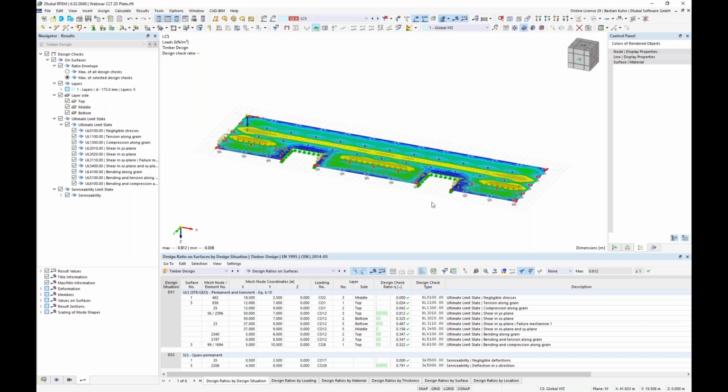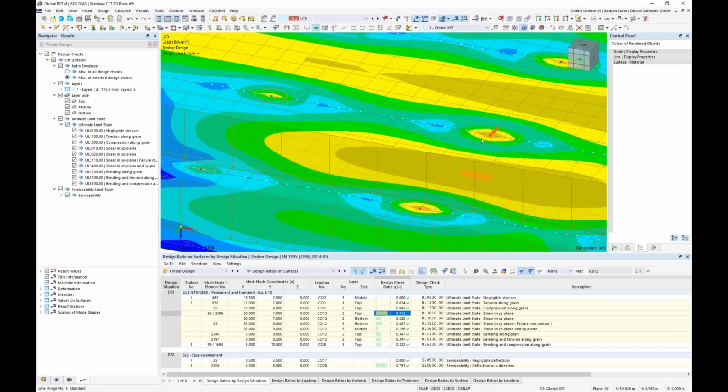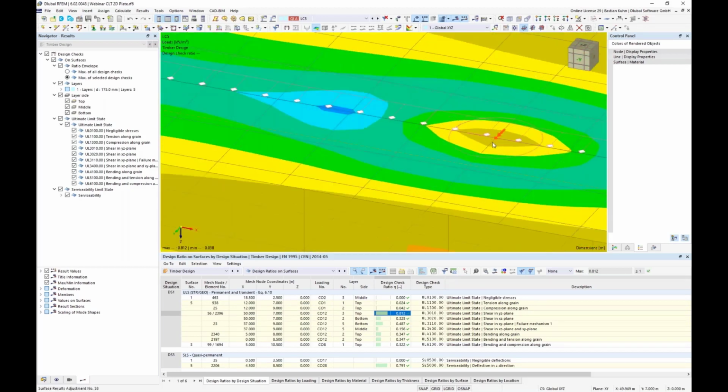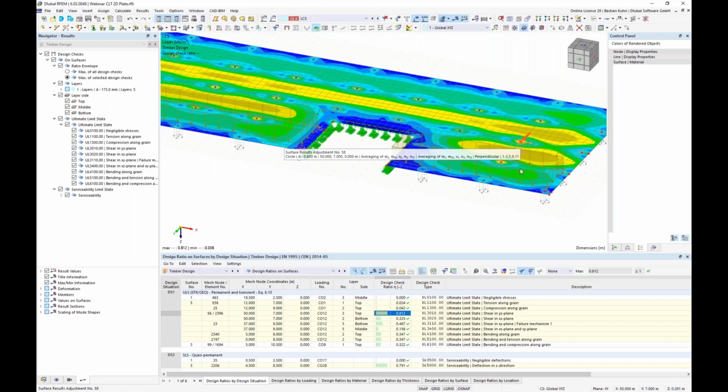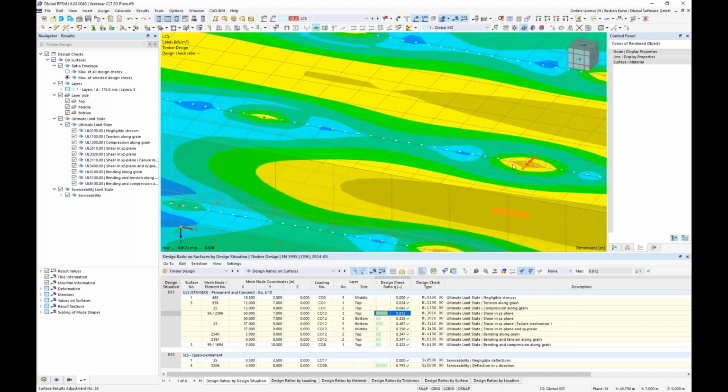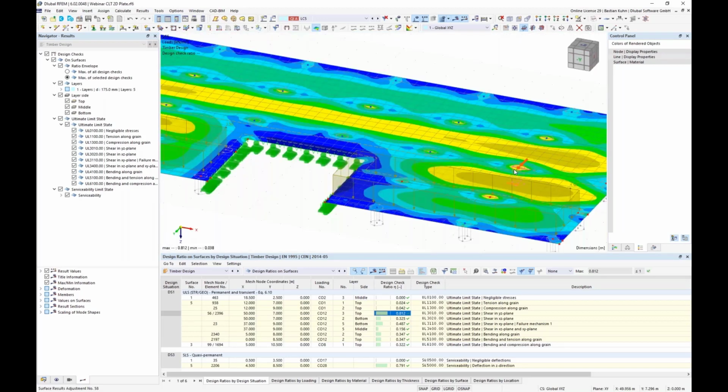And now we can take a look at the results and then just create a printout report and we are fine. Results are good now. So the overloading of 1.1 is now changed into a loading of 0.8. Of course, you should make a finer mesh in here. If you look in here, you see that the span is just smoothing it about this area. But in general, that's how it can be done, or how to regard the punching in here and how to avoid this overloading.